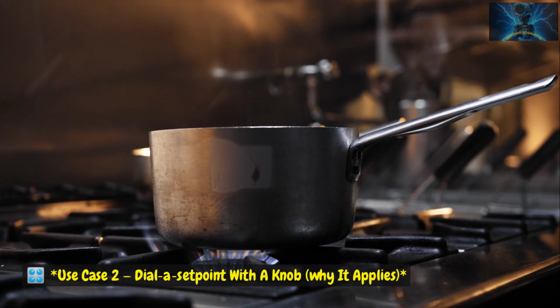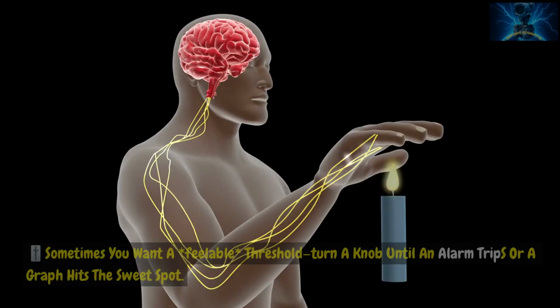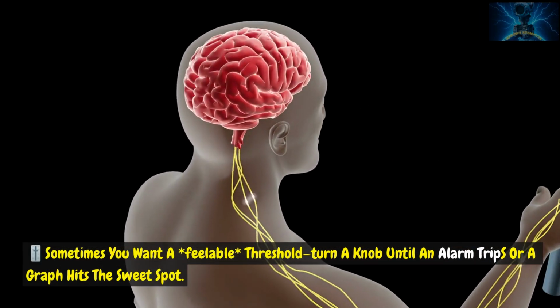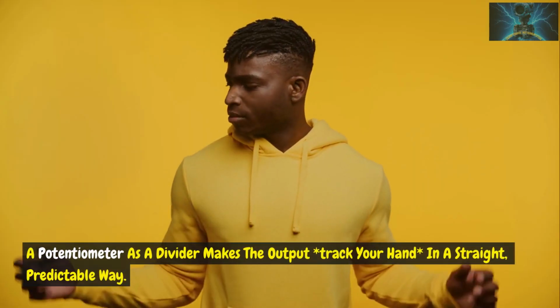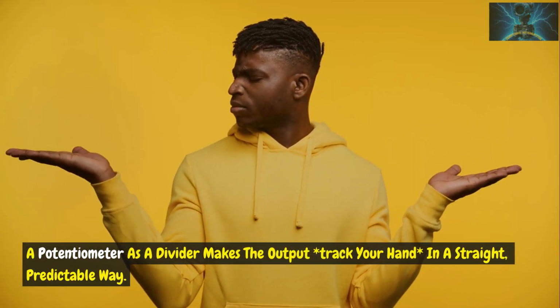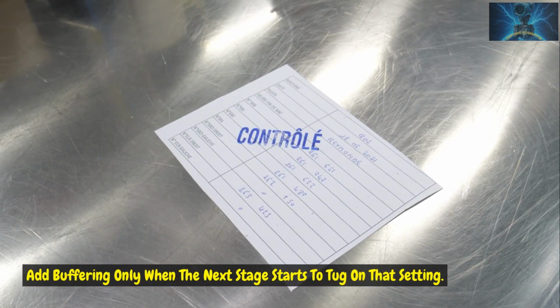Use case 2: dial a set point with a knob. Why it applies: sometimes you want a feelable threshold. Turn a knob until an alarm trips or a graph hits the sweet spot. A potentiometer as a divider makes the output track your hand in a straight, predictable way. Add buffering only when the next stage starts to tug on that setting.